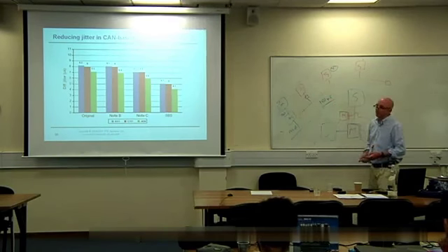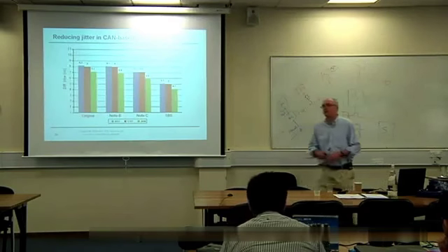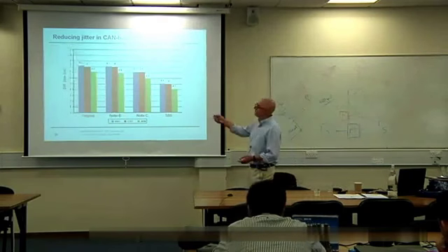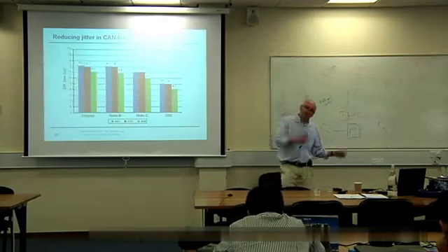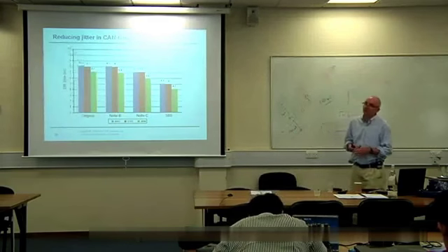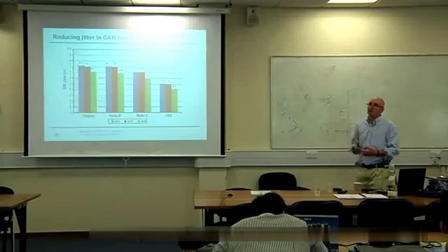What's causing the jitter? Latency, right? Essentially the jitter is caused by the fact that the different messages will require different amounts of bit stuffing. So how do we ensure that we have a fixed amount of bit stuffing?